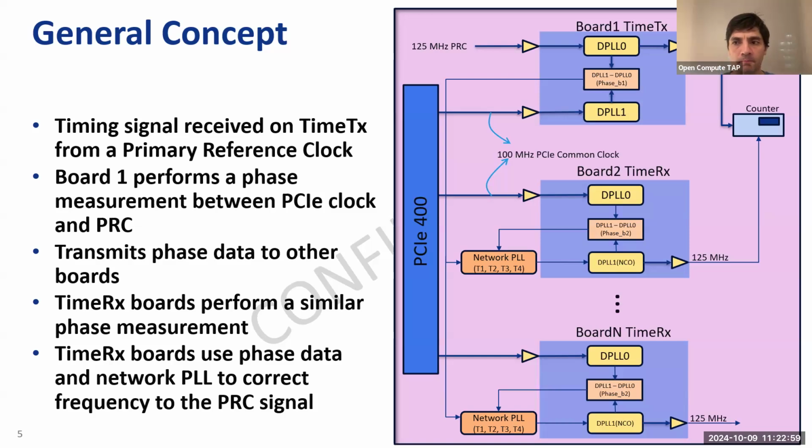Simon? Yeah, I'm just thinking about that. I did not test this with spread spectrum on the PCIe bus. I was just using a 100 megahertz clock that had the same specs as the PCIe bus 100 megahertz clock. So that would be something I would need to try with spread spectrum.